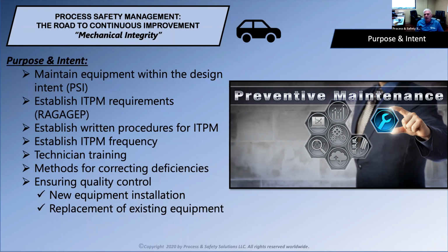New equipment installations are per RAGAGEP or to the OEM requirements, and the replacement of existing equipment is to those same standards. Oftentimes, I will get asked the question about MOCs and should I do an MOC on this or that? And it really comes down to design intent for sure, but also you need to go beyond that.